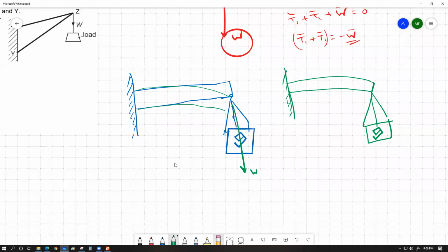So my point is, whenever we have this kind of a curvature or arc, what actually happens? The outer side experiences a tension force, for which it bends like a curve. So this outer part undergoes extension and the inner part undergoes compression. And the total object undergoes a composite scenario of deformation where you have both extension and compression within the object at the same time. This is the scenario that we call bending.